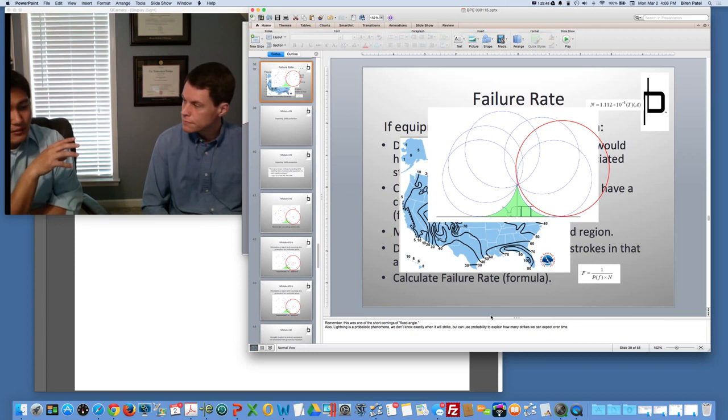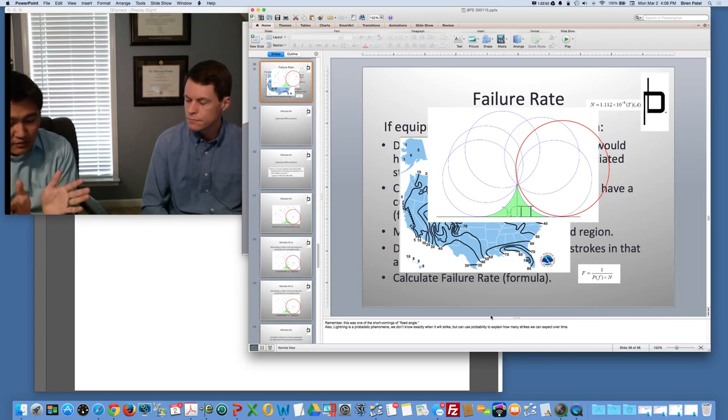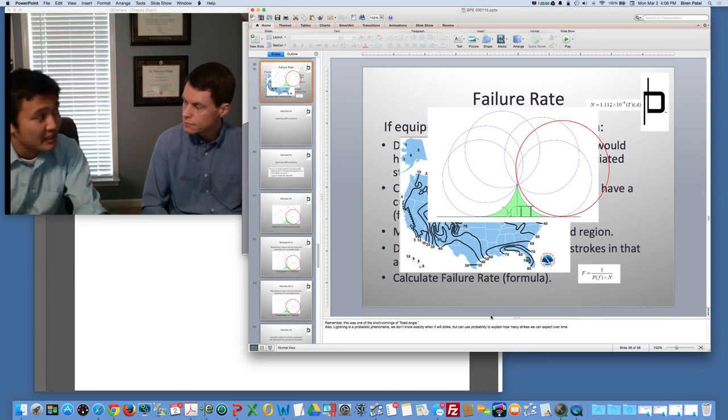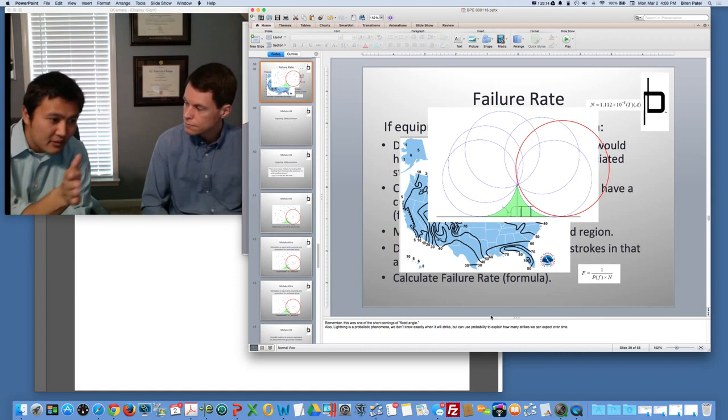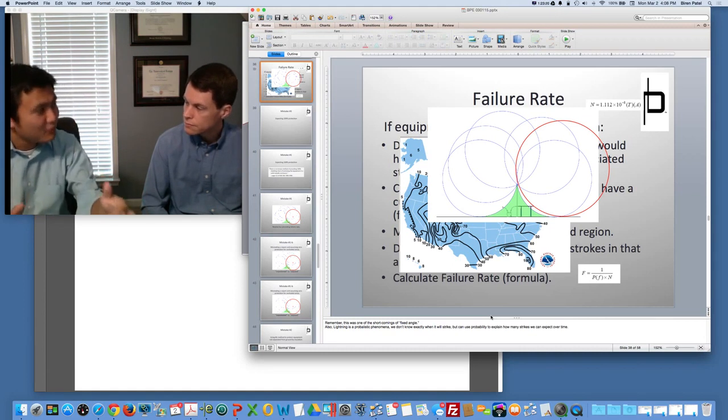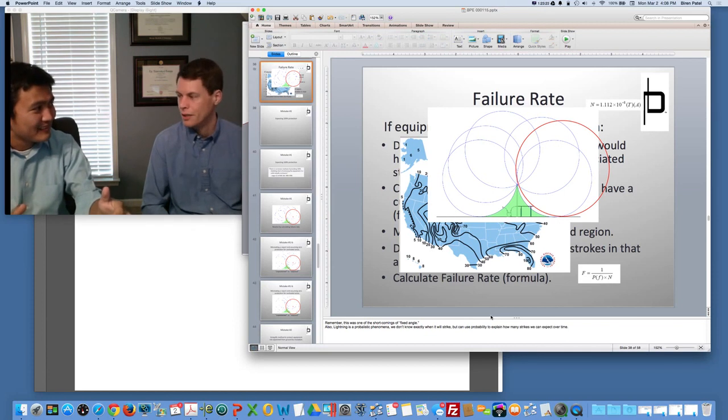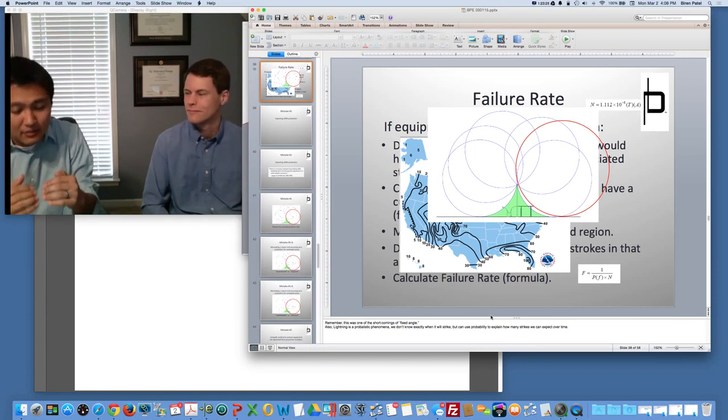And if a substation is going to expand, that's something to think about too. Let's say you've got a substation built and you've got it to 1 failure every 100 years, but you've only halfway built the substation. And 10 years from now, you plan on expanding that substation to double the size of it, and you put in the same level of protection. Well, you have 1 failure every 100 years in the old half, and 1 failure every 100 years in the new half. As a whole, your substation now has 2 failures every 100 years.